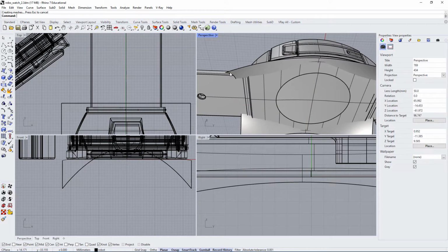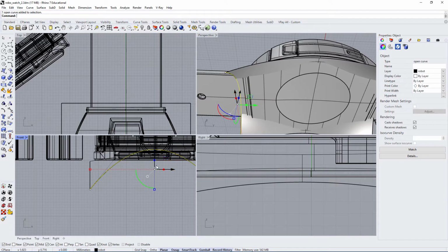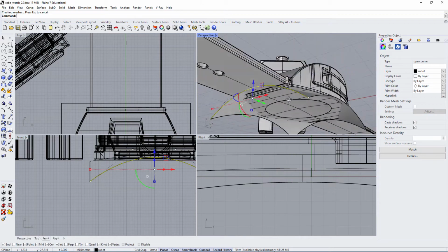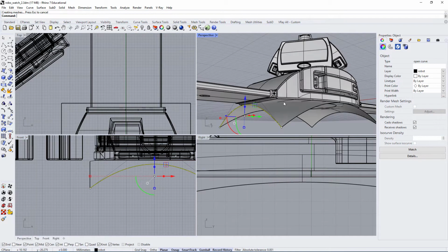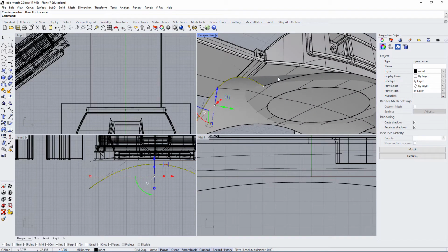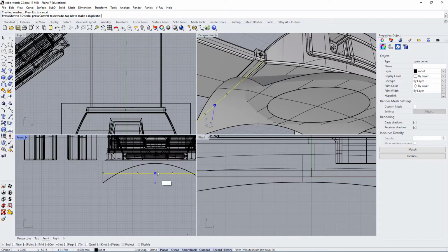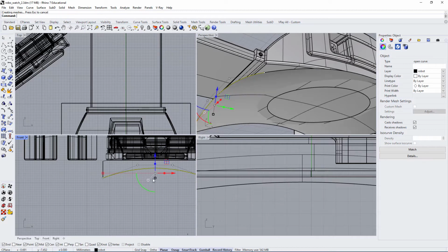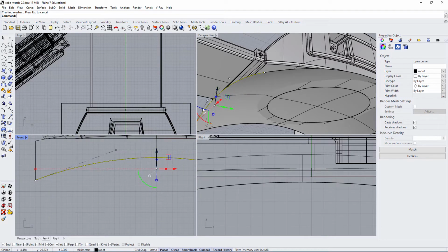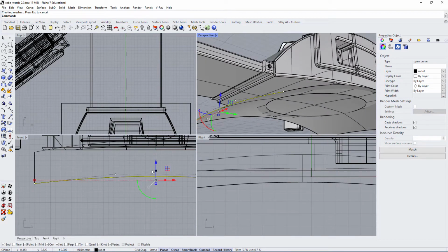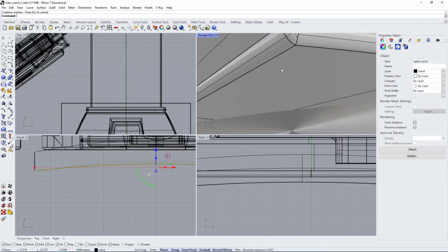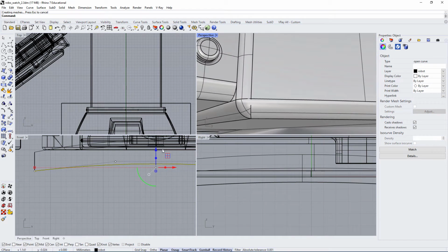And then I will adjust this edge profile, and I will use the scale command. And let's say we want something like this. Okay, so we'll do the opposite. We'll remove curvature so that the center profile is very curved and the edge profiles are less curved. And what that should do is allow us to get closer to that edge.